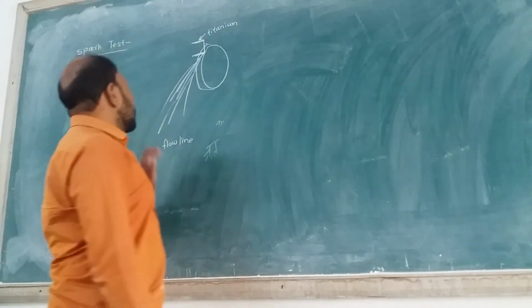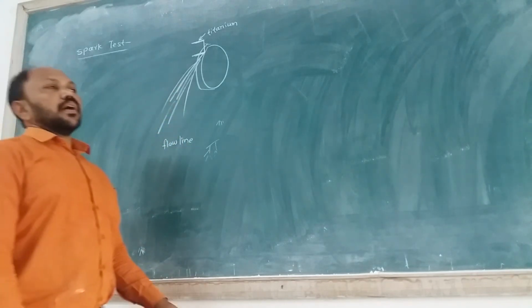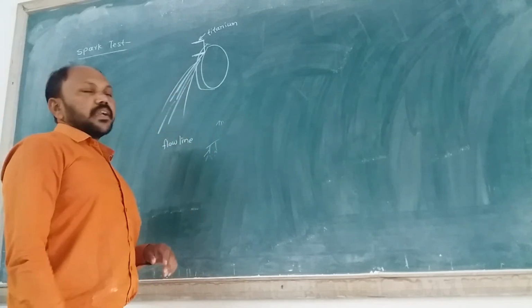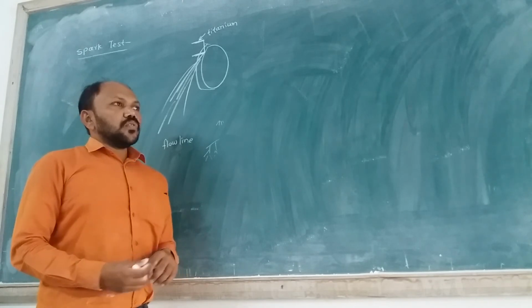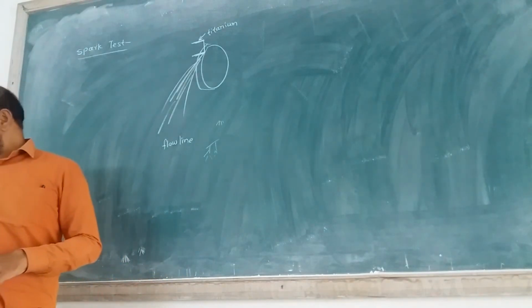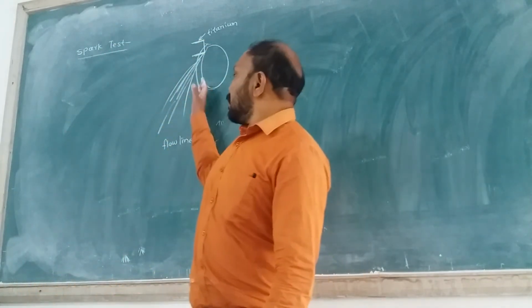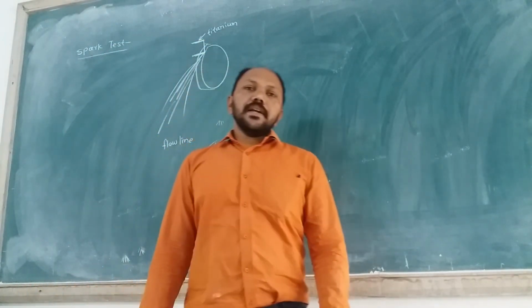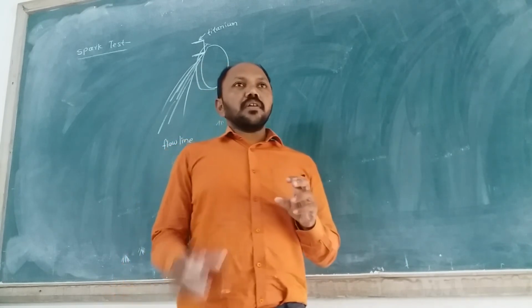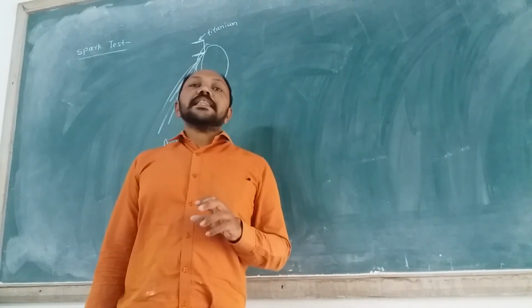So this type of pattern is seen in case of titanium materials. If the materials are made with forging, then it shows these flow line structures, and these flaws or bursts are not present in that case.